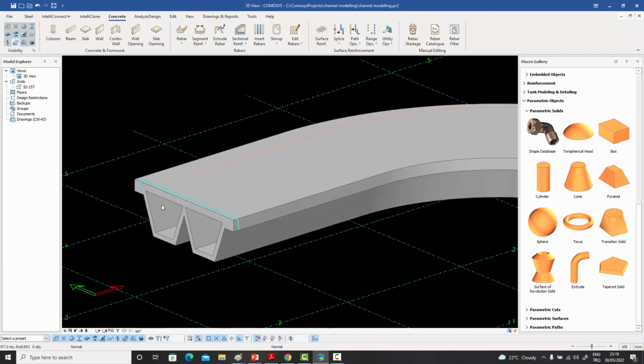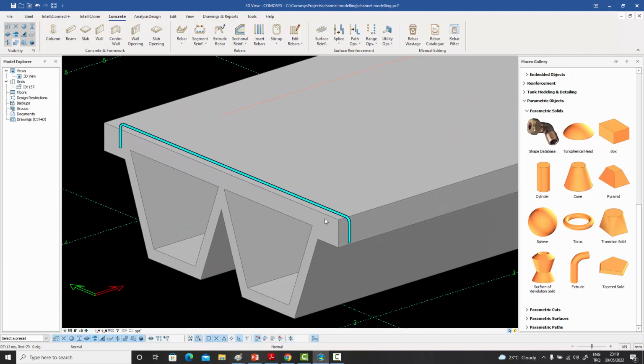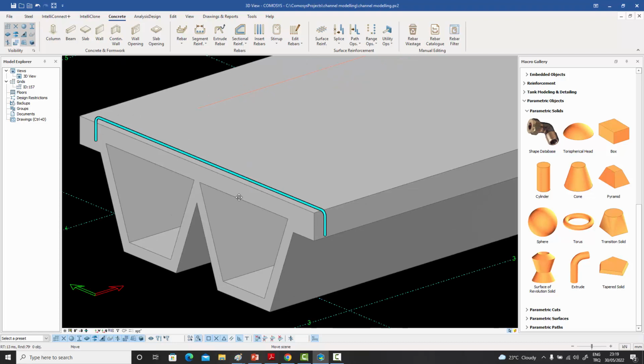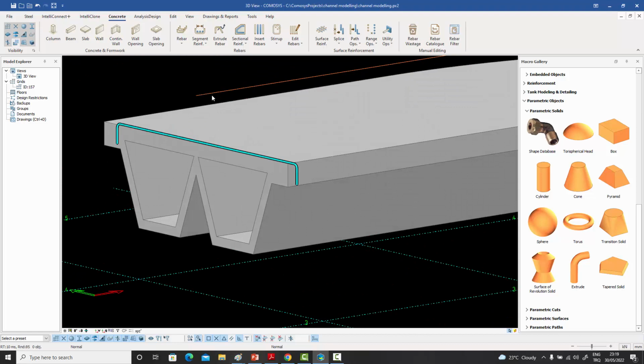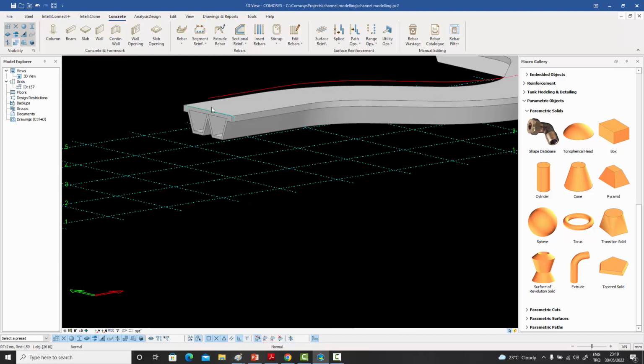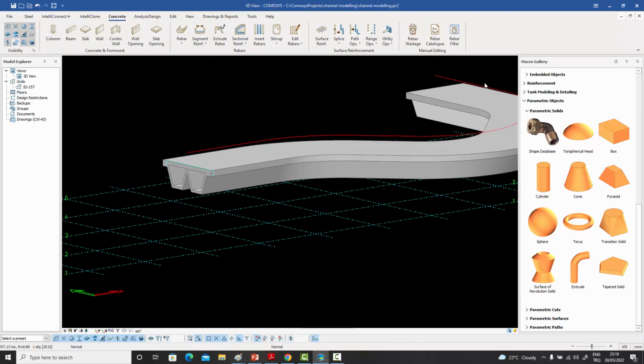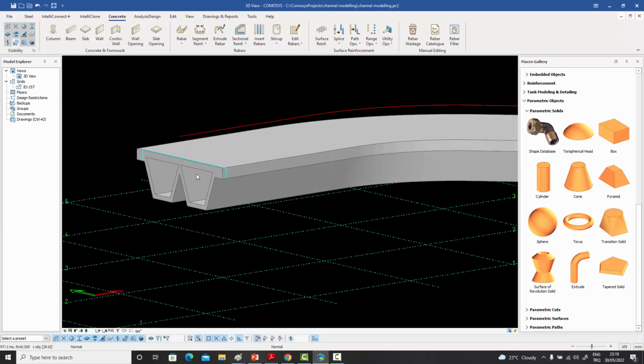And then, using the section command, I've created this bar inside it. We can create many bars with the section command around that and do the whole thing in one go as well, but I've created just one, and I have this path of the bridge over there as well. This is the curved path which I used for extrusion of the bridge.